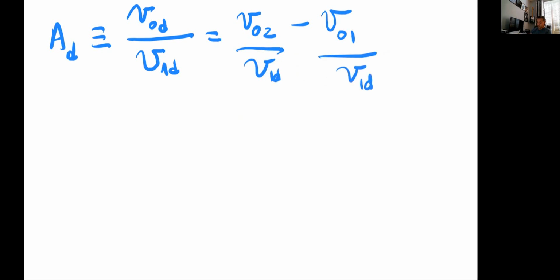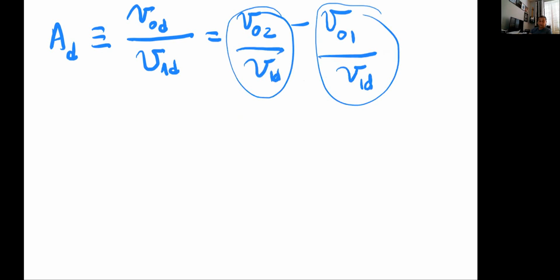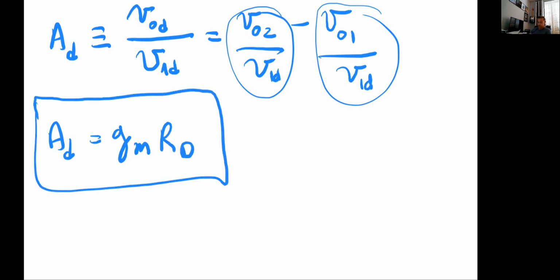and I wrote expressions for this before, I get this very nice, very elegant result, that the differential pair has a gain similar to a transistor. So it's a differential pair, but it behaves as a transistor because the differential gain is GM times RD. That is what a single transistor common source amplifier has, except that it's negative.